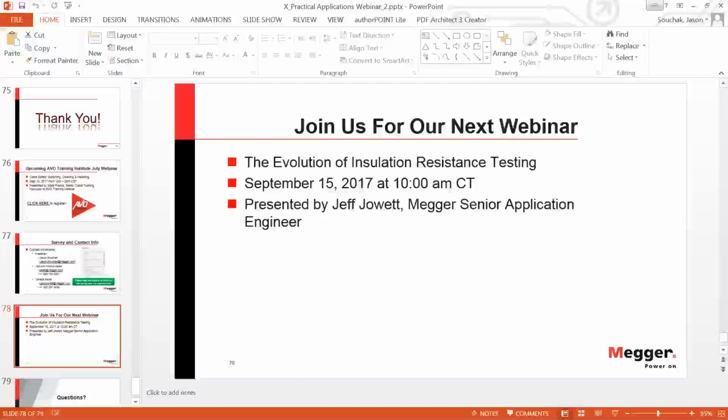Okay. Thank you, Henning. Next question is for Jason. For failed cables, what is the minimum length that is required to analyze the failure? So I'll answer this based on the individual tests that we talked about. For VLF withstand testing, I can test as small as you can make it. Any cable that you can put 2 terminations on and have something between, VLF withstand testing can test it. Practical length, really, 30 feet. I don't think too many people have something much shorter than that.